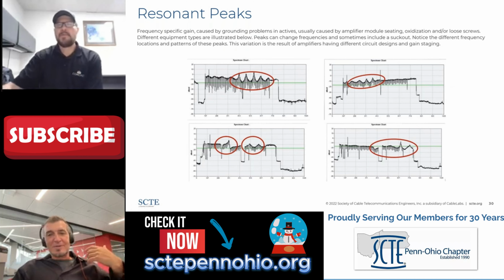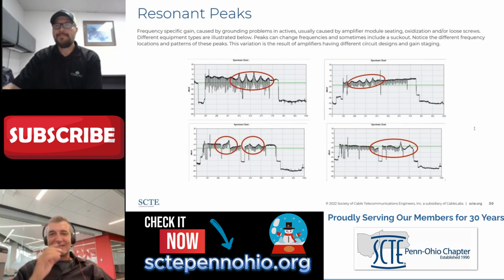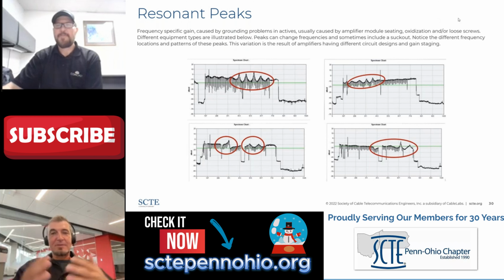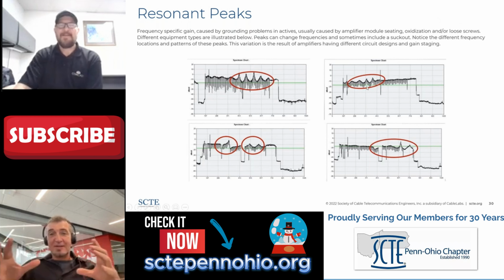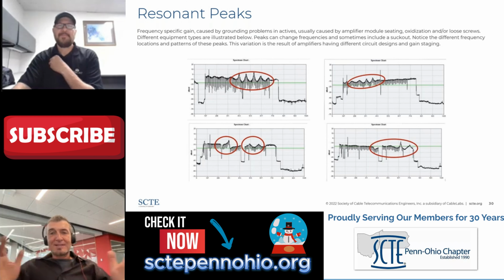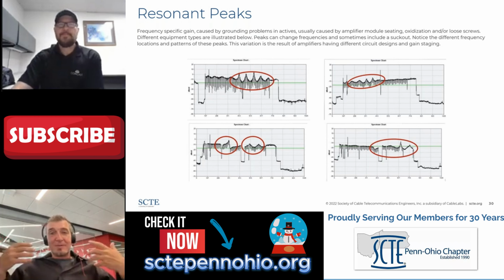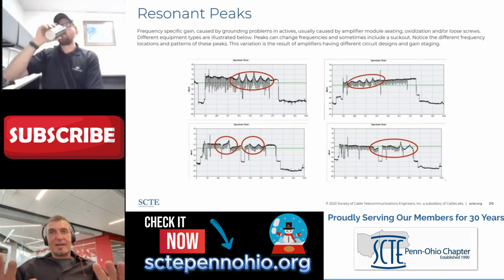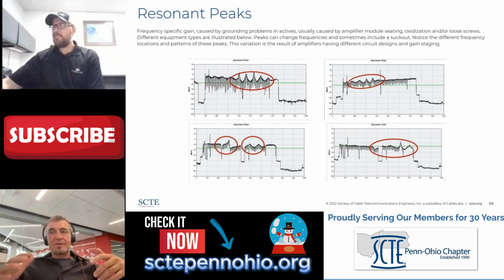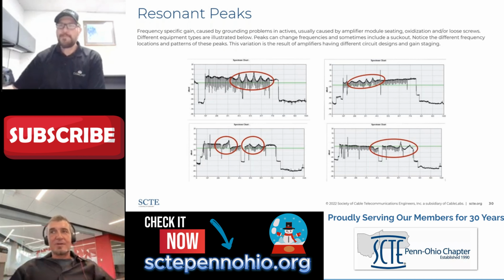And I almost always see, we just go boot the pedestal and it goes away. That's very temporary. You guys already know that, because it comes back and it's a function of that mechanical interface. So take an extra minute, maybe pop the module completely out. I know that can impact the customer. Put the module back in, hit all of the screws. Again, who do you see out there with a torque wrench? Not very often, but consider getting a torque wrench, but absolutely the torque sequence.